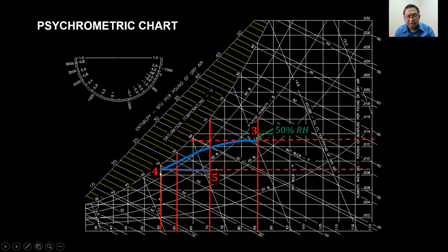And we have measured it at 55 dry bulb, 54 wet bulb. And so we need to reheat it. After removing some moisture in it, we reheat it to 70 Fahrenheit dry bulb, so we will reach point 5. So it will just be a horizontal line here. So you can now read up the properties of air at point 5.